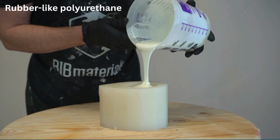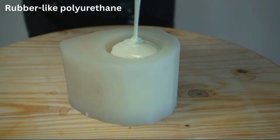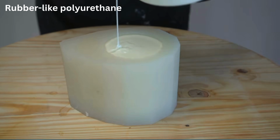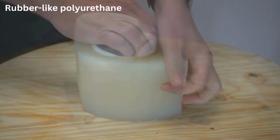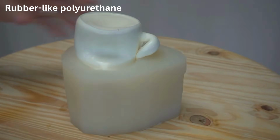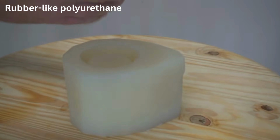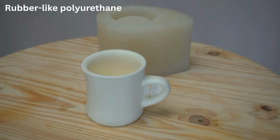Composite-filled resins incorporate glass fibers, ceramic powders, aluminum, bronze, stainless steel, or mineral fillers to improve stiffness, wear resistance, thermal conductivity, or metallic appearance. Certain silicone molds can also accommodate low melting point alloys, particularly tin bismuth alloys with melting temperatures below approximately 150 degrees Celsius, enabling fabrication of decorative metallic components and specialized engineering parts.